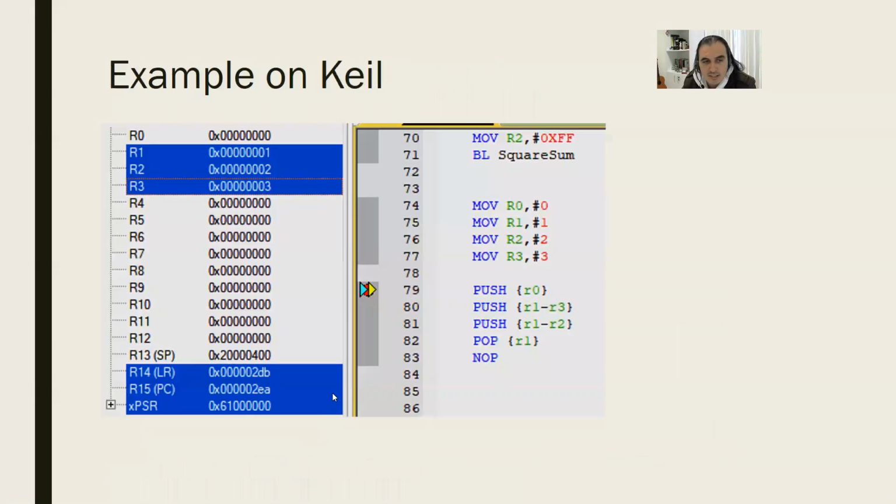It means that you have these values inside. When you push the value of R0, what happens? You push that value, get the value inside R0, and write it to that specific location, right? And it's the same. R0 is a 32-bit register. LR is also a 32-bit register, and there's a 32-bit value inside it.